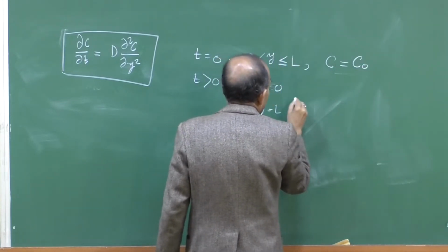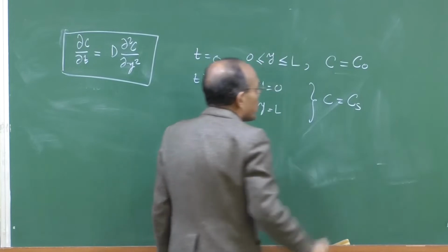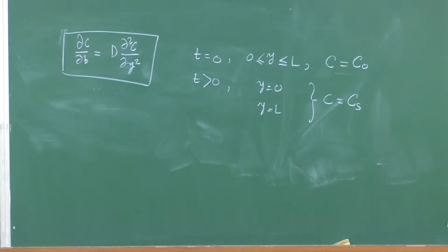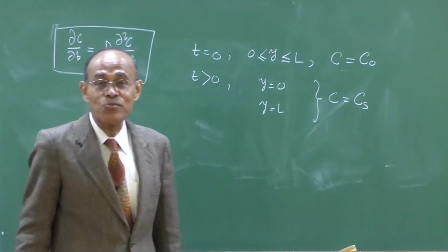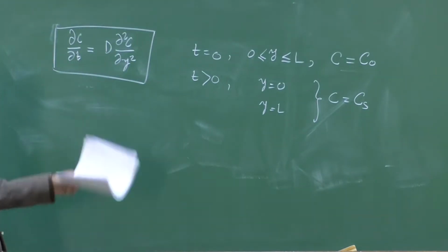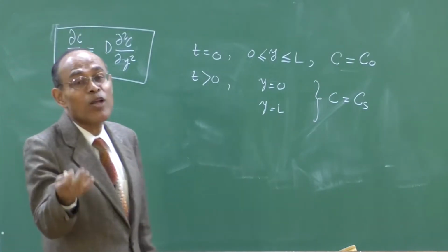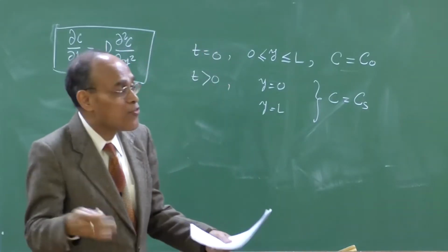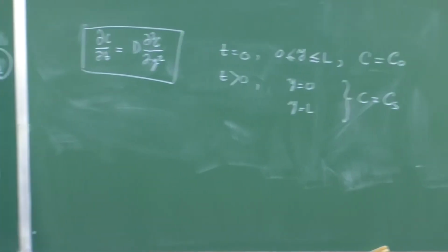Notationally we use C is equal to the surface concentration. So, if you remember your metallurgical kinetics fundamentals, you must understand that when you are solving the diffusion process, particularly when a species diffuses in a gas diffusion process, like for example carburization with the gaseous atmosphere, nitrogen diffusing into steel, etc. So, you will find that diffusion is preceded by a chemical reaction, which may be a dissolution reaction, which may be a chemical reaction.